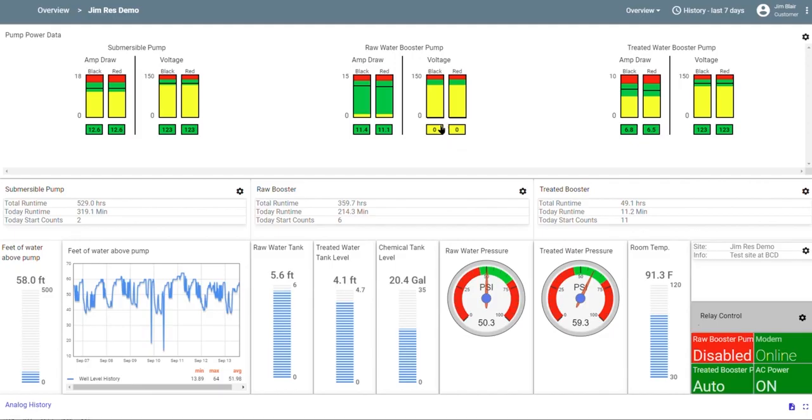About 10 seconds later, I get an alert by text and email that my power is too low on that pump. This is a pump man's best friend. Many of the high-tech controllers we have these days need to be reset to clear a fault condition. The way that we do that is turn the power off for a few minutes, and that clears any faults. Now we can do that from our office and save you the expense of a service call.